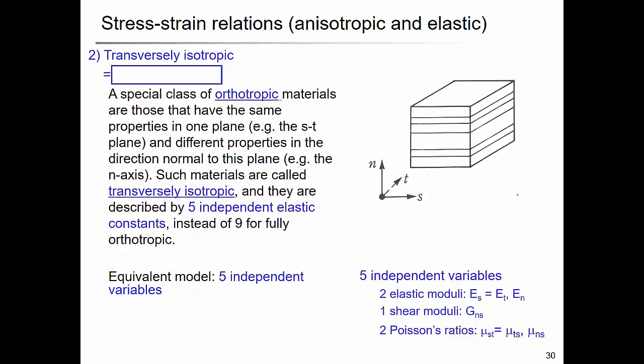And in soil mechanics and also geology and resource engineering, we generally use the assumption of transverse isotropy. That means you have different layers, or different stiffness along the z-axis. As you go deeper, in general, you have higher strength, or higher stiffness. So this is called cross-anisotropy. But in the plane, the x and y axes are all symmetric, right? So it's kind of an axisymmetric condition. Transverse isotropic, in this case, has 5 independent elastic constants, and here the Young's moduli in the x and y axes are the same.